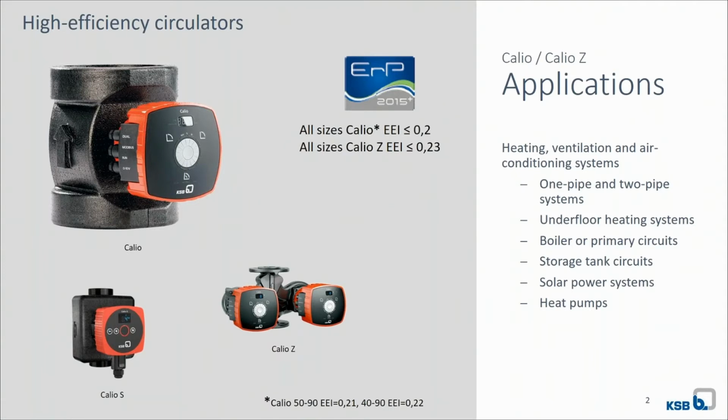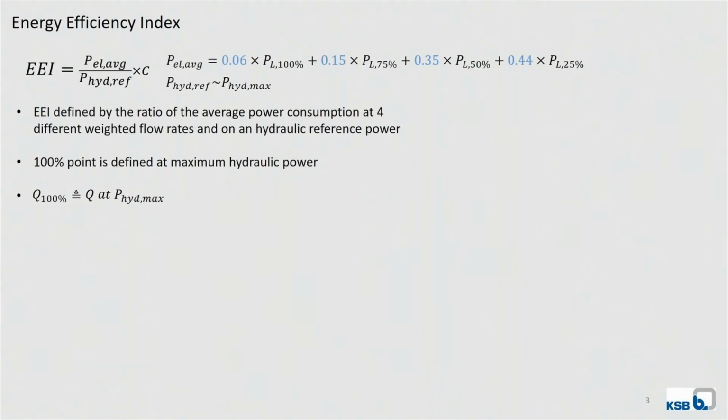Yeah, the energy efficiency index is a little bit complicated to explain, and that's why here I will have a slide to explain this a little bit more. The energy efficiency index is defined by the ratio of an average power consumption at 4 different weighted flow rates and on a hydraulic reference power.